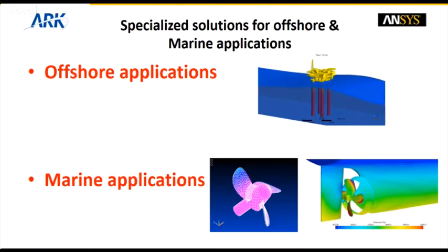There, the structure is inside a fluid domain, so whatever forces come onto your structure are due to the fluid domain around it. So you need to do fluid analysis, and by doing the fluid analysis, see what different stresses come into your structure. So this is based on two physics, structural as well as fluids.